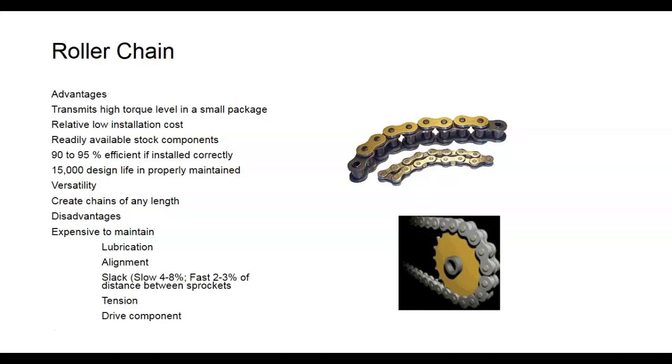I had a chain drive motorcycle, and the chain wasn't aligned exactly right, and it wore out the teeth on the sprocket. So I had to replace that. So you want it to run down the center, right? You understand that? And then, of course, we have to adjust the tension on these.